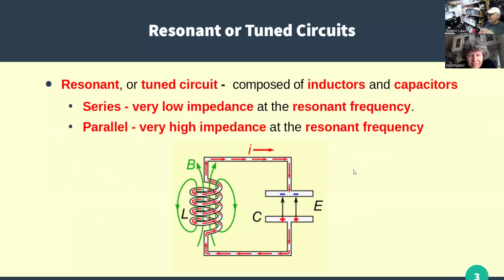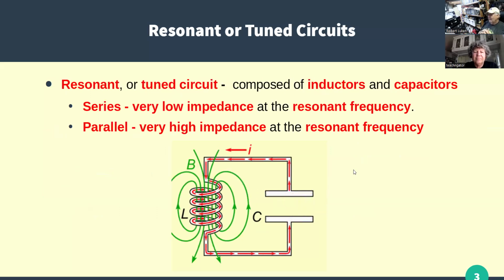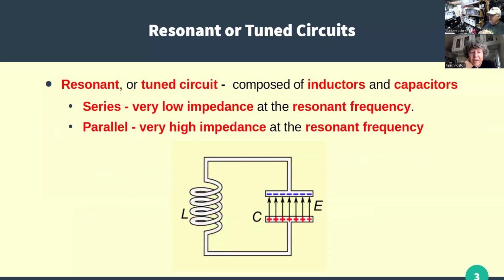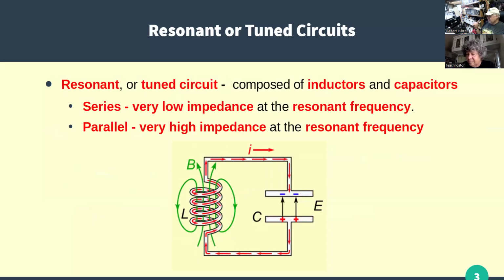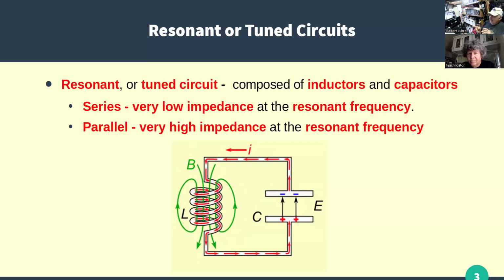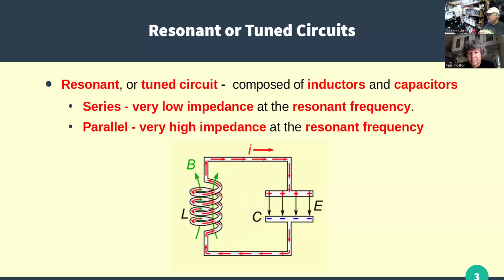Right, so when we have a resonant or tuned circuit, and we're looking at a parallel resonant circuit down here, the animated one, what you're seeing is energy being stored in the capacitor up to the point where current stops because it's charged the capacitor up. Now the capacitor starts to discharge and is supplying current through the inductor and building up a magnetic field.